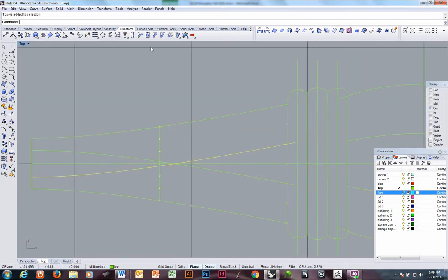Now I'm going to grab this non-uniform scale at this point, because the origin in a scale class is where you don't want anything to change. I don't want anything to change right here. I want that to stay. I don't want to scale in this direction, so nothing. I want to scale in this direction. I'm going to pull that out until it pretty much goes through that point.